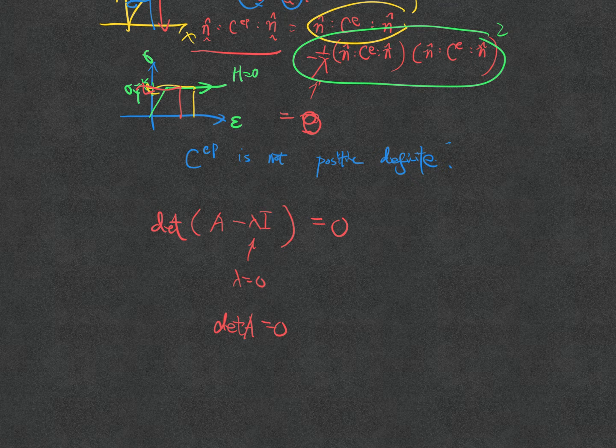So when it's not stable, what it means is that you can actually have a zero energy mode related to the plasticity. So you can get those weird shapes like a shear band, and one of the reasons is that C^ep is not positive definite. Okay, you can also have some other patterns that manifest from that, which you won't see from elasticity.